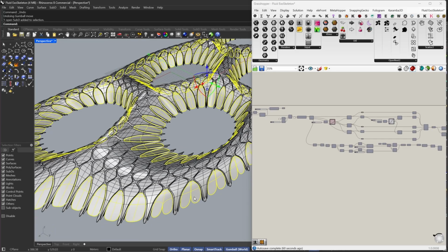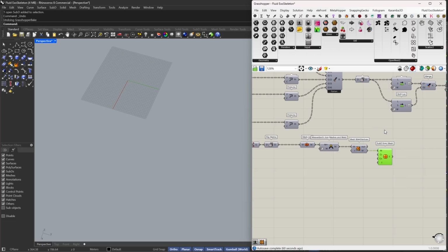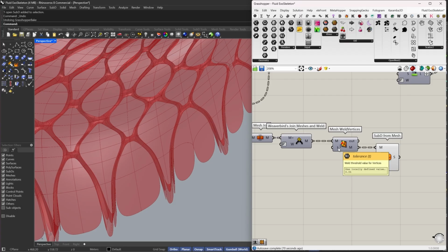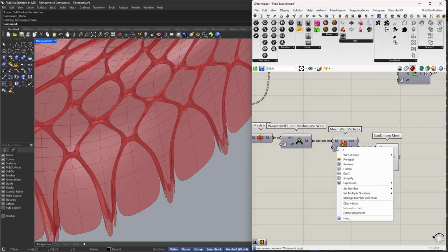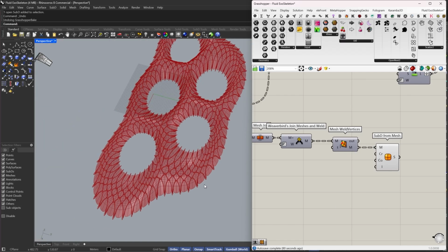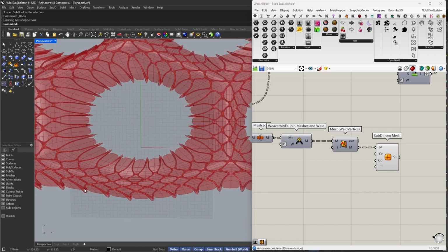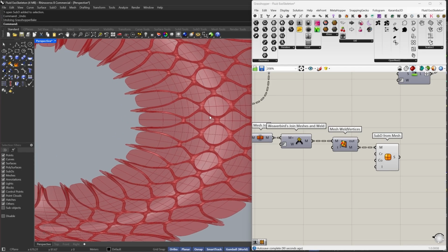First of all, these are not good, so we need to check on that. So let's try to see. These are not working well because the tolerance needs to be a little bit higher. So in this case, I'm going to say 2. I think 2 did its job. Hopefully nothing else is bothered. It depends, you can increase it, but do not increase it too much, because if you increase it too much, some of these vertices will crumble. So take care of that.